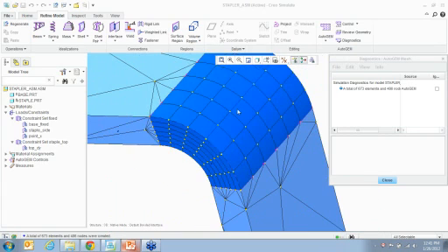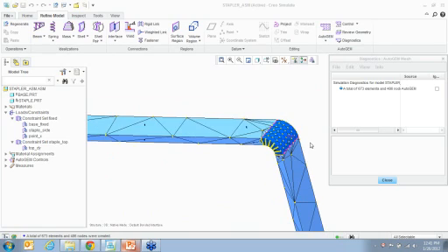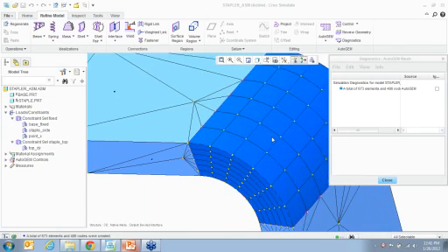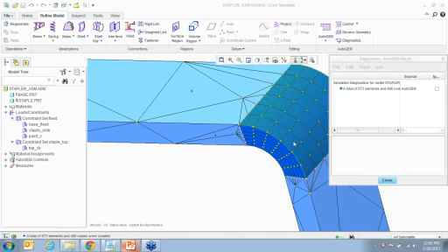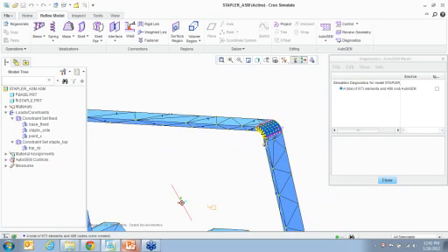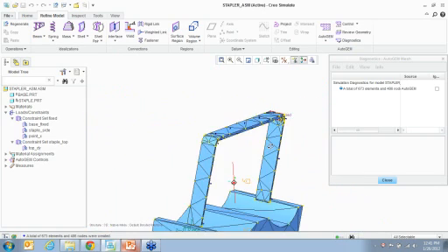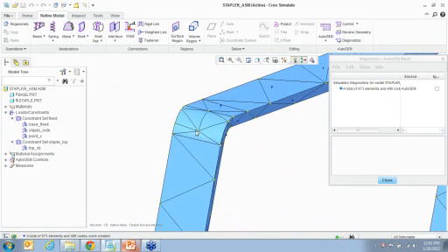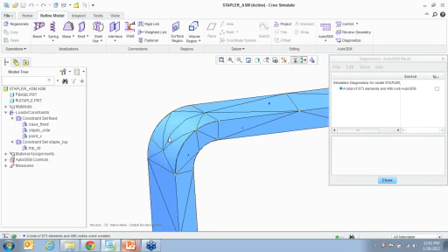I want you to see right here. That's more of a map mesh because this whole staple thing is going to bend over there. So this angle is almost going to be like flat. So you want to have more clear representation because there's going to be a bunch of stress concentrations. It's much more accurate if you have brick elements. So I'm going to create brick over there. And you notice on this side, when I don't create those brick elements, I don't get much clearer localized results.